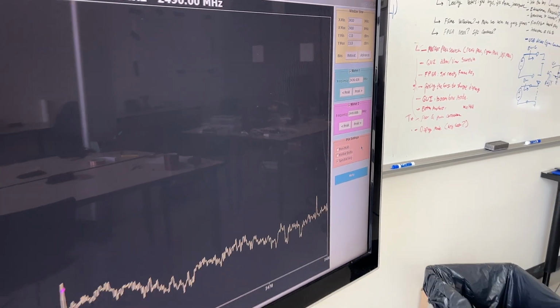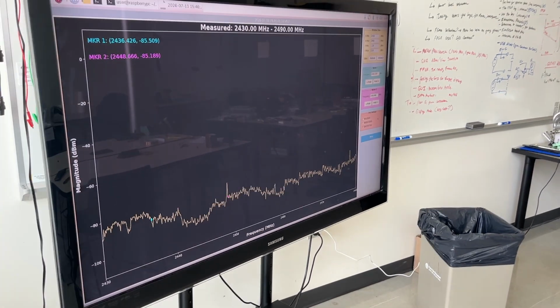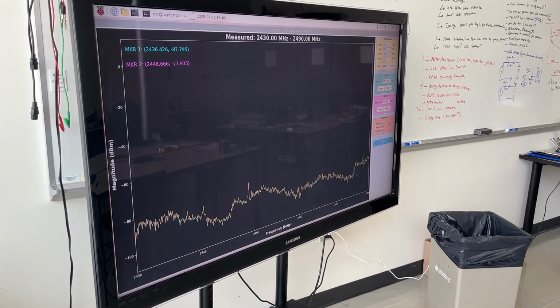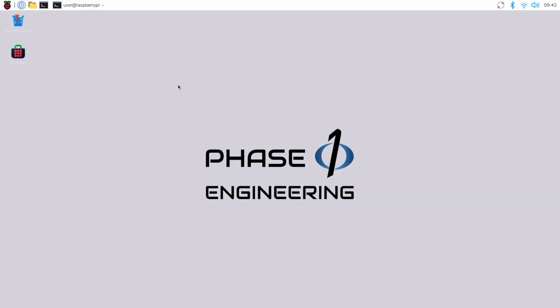For the most part, our system is bottlenecked by the communication speed from the Pi 5 to the FPGA. We originally thought our SPI communication speeds would reach upwards of 20 MHz. In the end, our practical limitation is somewhere closer to 5 MHz without packet degradation. That being said, we were able to get the device to operate in the entire range of interest with some limitations on refresh rate. Here we will demonstrate an example measurement of the Wi-Fi and Bluetooth band.